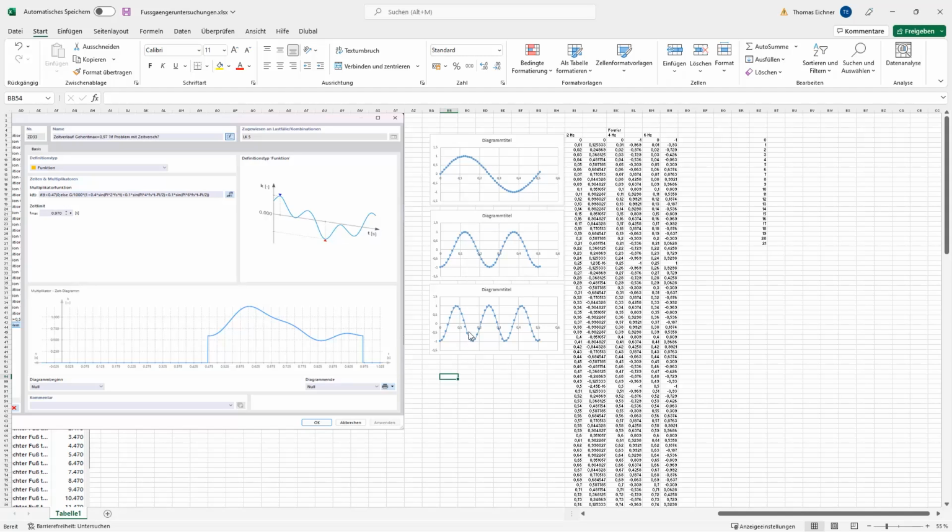With that, there's one more thing. I just didn't implement it in my function. But what you can see here is that the phase shift of the second and third harmonic makes it a minus cosine function, basically. That means the minimum of this whole function will not be at the 0 point, but a bit to the left side, depending on these Fourier coefficients. In our case, it would be 0.03 seconds shifted. And that's something we would need to implement in our function here as well, if we want to consider it.